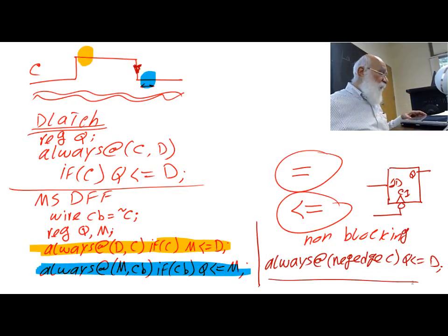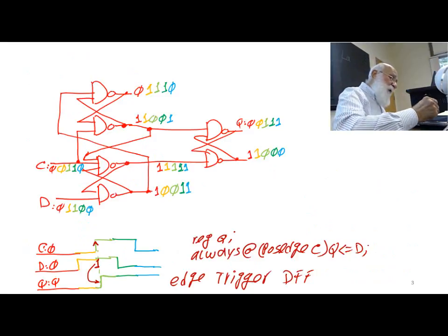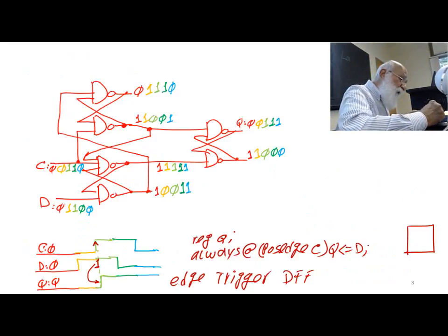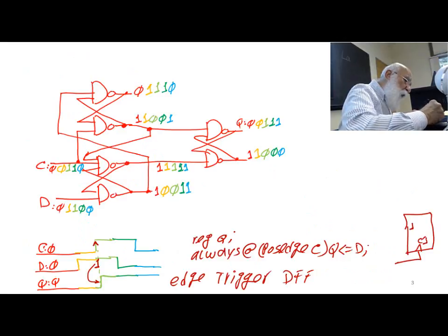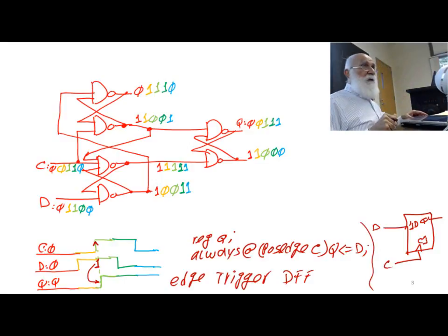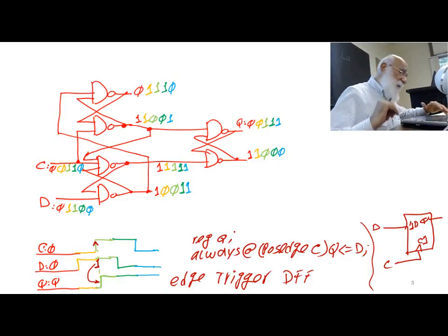And therefore, going to this one, the symbol for this is C1, D, Q. And then again, I'm showing that my D input depends on the clock input, but then with the clock, I'm showing that triangle, meaning the rising edge. If I put the bubble next to the triangle, then it's a falling edge. Okay?